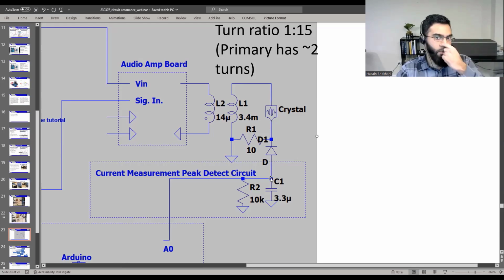Then when it oscillates and comes back again, say the first sine wave was 5 volts, about 4 volts got charged on the capacitor after a couple of cycles. Then a higher peak of 6 volts comes, and the capacitor gets charged higher. It keeps that value because the charge can't drain back. You're not allowed to drop the voltage because the current can only flow one way.